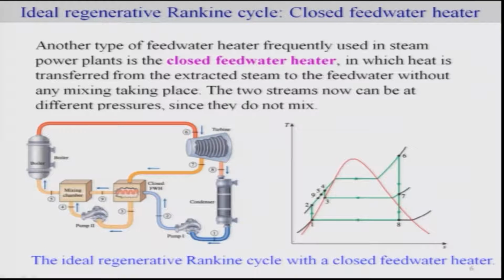So, the process is the same. For example, you can consider 6, which is your working fluid, and here this is your stream, which undergoes some part of it being extracted as 7, okay, and this is at a different pressure. So, you can see this is at pressure P dash. Okay. Now, the rest at 8 isentropically expands until it reaches the condenser pressure.